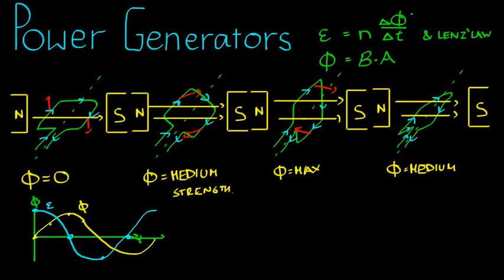If we had slip rings, and slip rings basically say we have a circuit built around the motor, and this wire of the circuit will only connect to one wire of the coil at all times. So say this wire here connected to that one there, it would connect to that one there, and that one there. So even though it's rolling around, the slip ring assures it only ever connects to this end of the circuit, and this wire will connect to this wire, therefore this wire, and this wire.